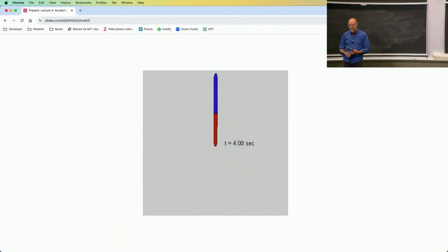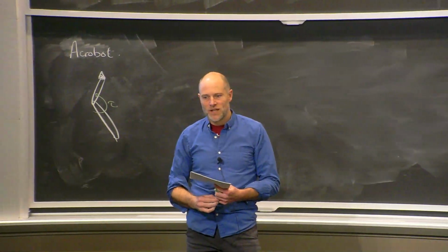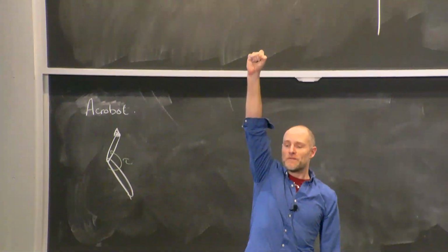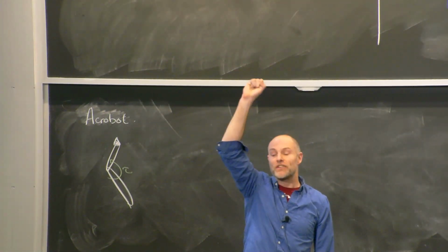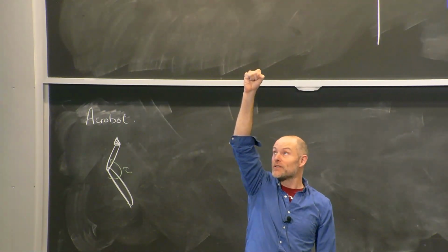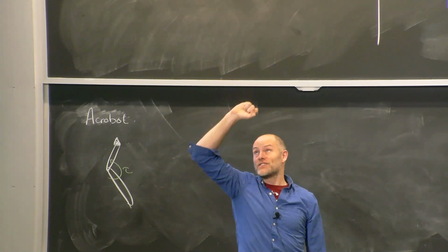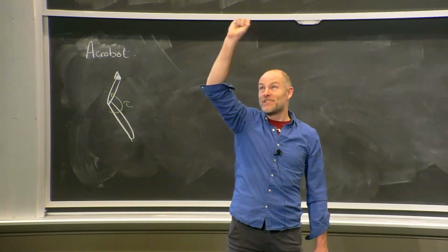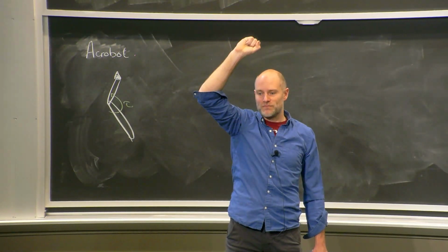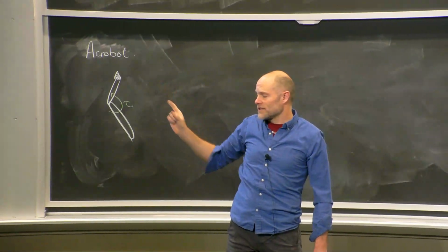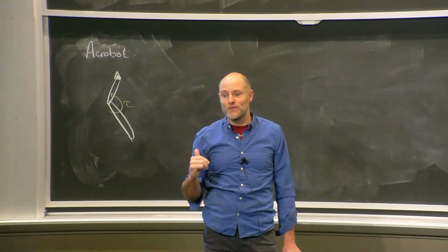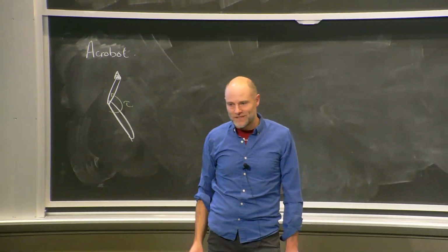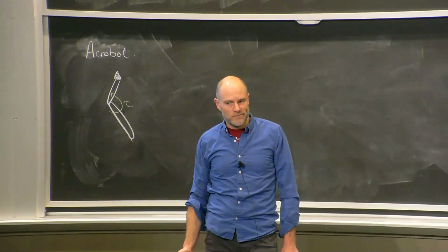Yeah, backlash is annoying, right? Yeah, and stiction actually is the other. So if you're perfectly here, you're never exactly at the fixed point. If you're anywhere but the fixed point, you start falling. And you actually have to take some sort of gross movement, because it's non-minimum phase, but you have to overcome your little bit of threshold because of the stiction and the backlash. That's actually an actuator that we worked hard to reduce any backlash and stiction. It's a belt drive that's carefully designed to minimize that, but it's still tough.